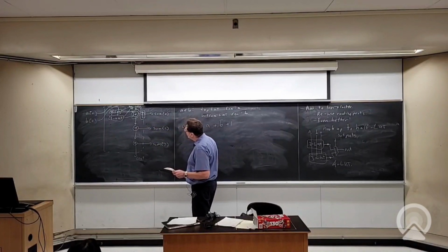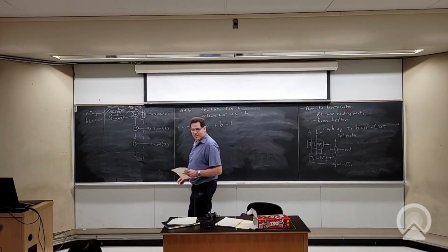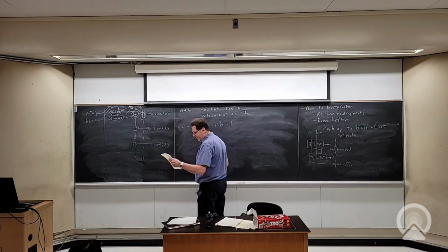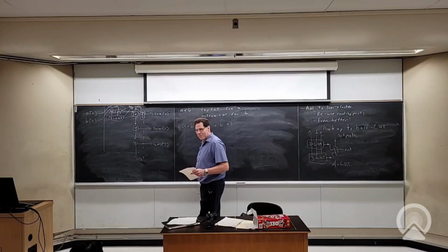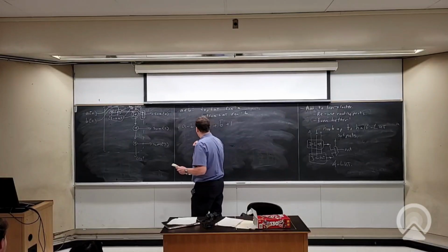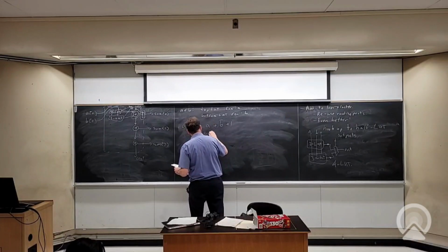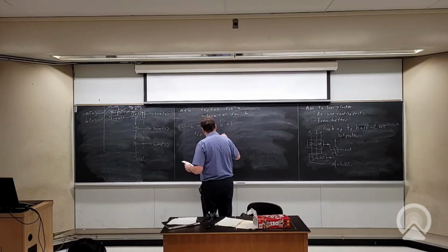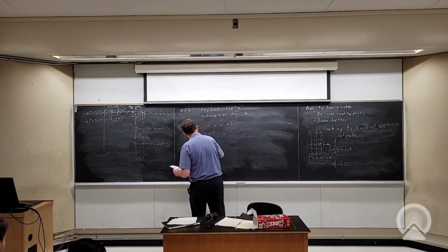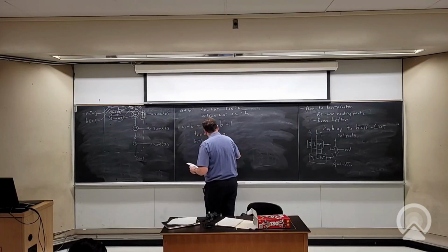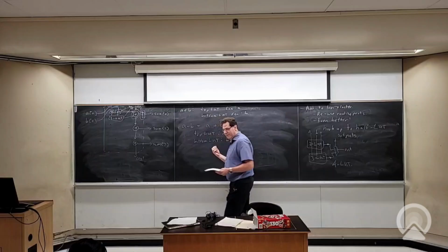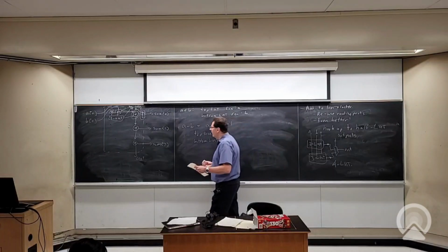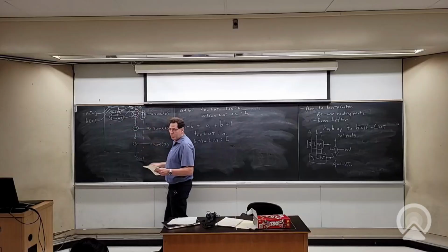I think. Let me think about that. I guess it doesn't really matter. I guess I'm being vague. You can tell me whichever one you want, right? So which one do you want? You want the top LUT to be which one? Okay, so top LUT is A, let's say that. Then what do you want the bottom LUT to be? Okay, and the bottom LUT then is B bar. Okay, so that'll do a subtractor. And we also have to set our C in to 1, but we can do that too.